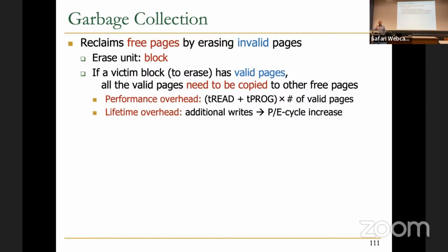In a hard disk drive, there is no such thing. The number of writes that you send to your hard disk drive is the same as the number of writes that happen internally. But for an SSD, I might send, for example, 1 million writes to my SSD, but internally my SSD wrote 1,200,000 writes because of these operations.